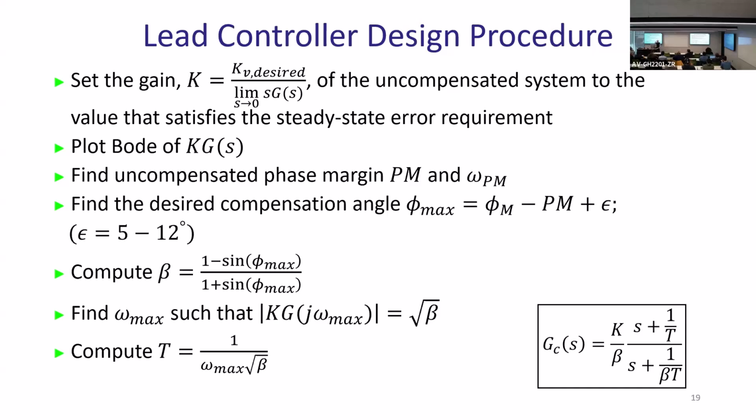So why do I want that particular ratio to be my additional gain? Because what happens is my open loop transfer function will be K times G, right? That K that I defined here. So what is K times G? It's whatever number times some DC gain or Kv of that function. So if you want to compute Kv of the overall function, what will it be? It will be limit of s times K times G, right? So substitute that K in there.